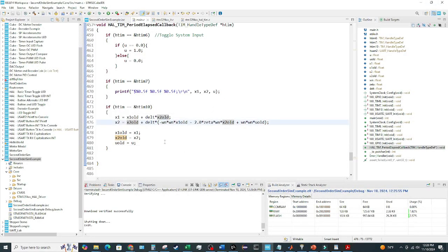We'll be building on this. The final project will be simulating the motor and driver, which is a first order system, being controlled by some kind of controller. So we may have a multi-order system for our closed loop transfer function. By the time we add maybe a PID controller or something like that, I don't think we'll get much higher than a second order system.